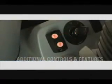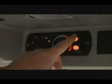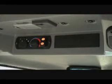The hydraulic implement lockout switch is located on the right console. The down position is unlocked, and the up position is locked. The heating, ventilation, and air conditioning controls are in the overhead module built into the headliner. Since this HVAC unit is powered electrically by the accessory power converter, it delivers maximum performance even at low idle. The radio is also mounted in the overhead module.